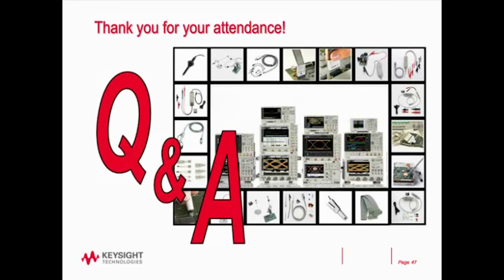Okay, I think you sort of mentioned some of this. Can your new power rail probe be used with the PSRR measurement? Not today. We just introduced this power rail probe. Today I recommend using a one-to-one probe, which limits the bandwidth, but it's a relatively low bandwidth measurement anyway.